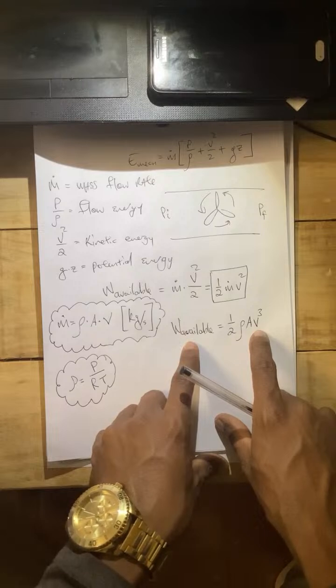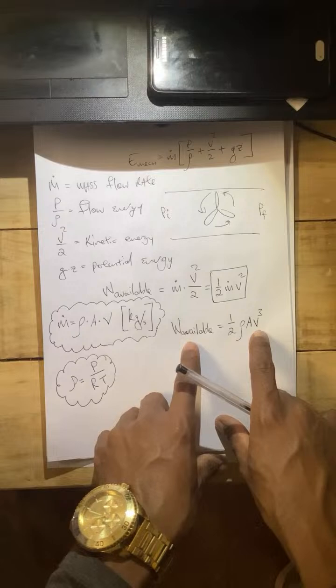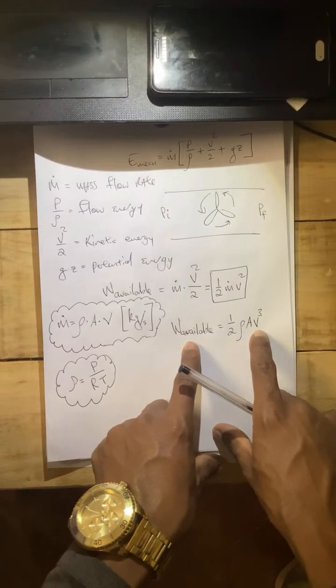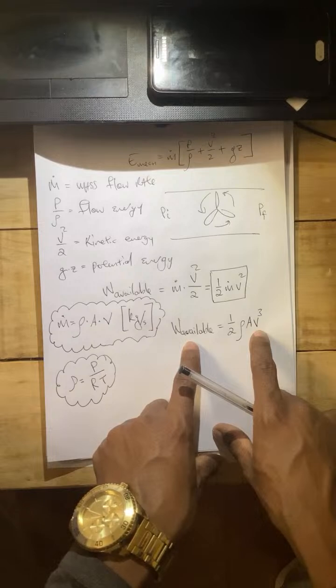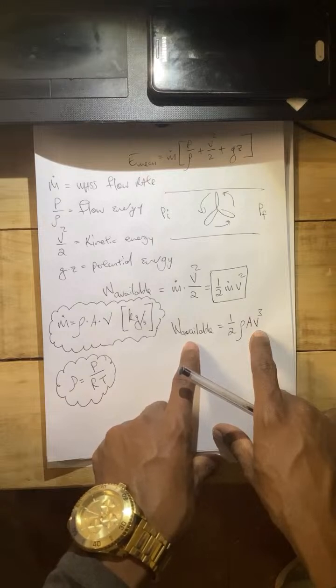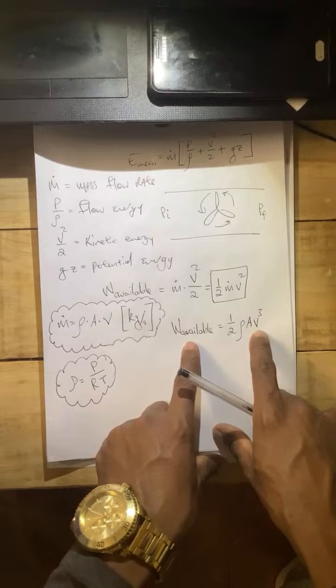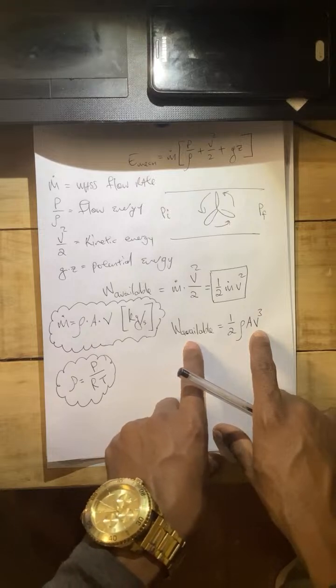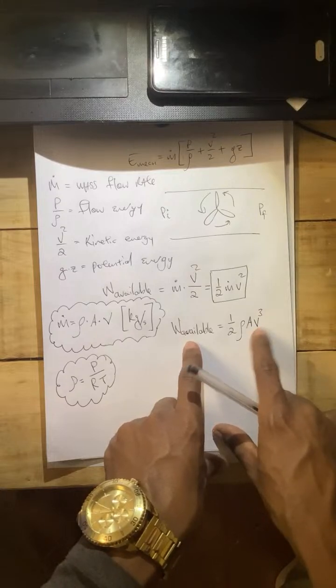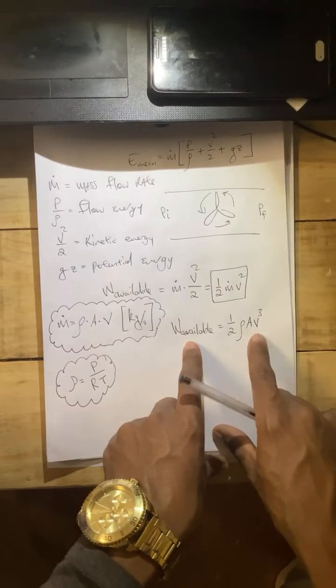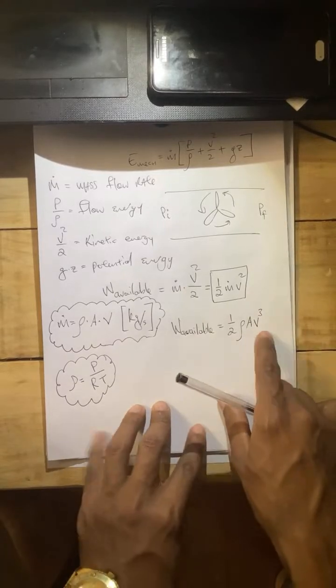Now let's take the speed from 2 to 3. If it's 3 to the power of 3, it's 27. That means your multiple goes from 8 to 27. So if your speed is 1 meter per second, 2 meters per second, and subsequently 3 meters per second, your power output will go from 1 to 8 to 27. Imagine that. And that's why this is important. However, and this is actually what's key.